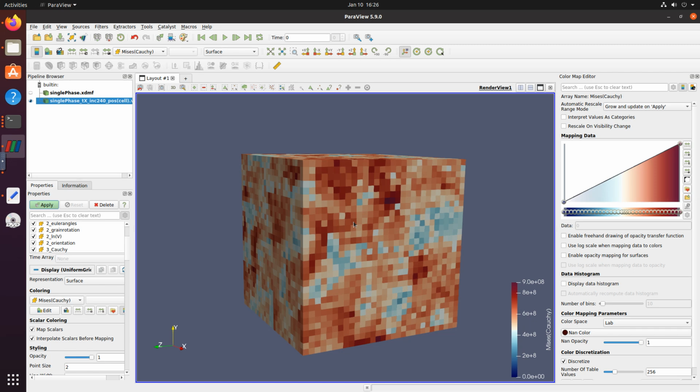Ideally, the global response, the stress-strain response on average, will not change for the material. But of course, the local response for one pixel might change. Where there was very high stress at one point, now that it is relatively away from the grain boundary, the stresses might change there. So the local results probably do change, right? This is what we have observed in the past with all the simulations and all the cases, but the global results do not change.